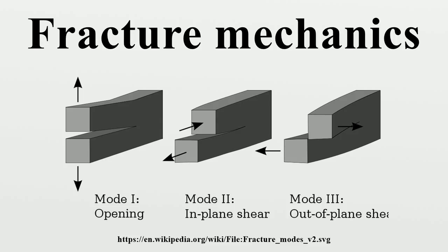Other approaches can be used to determine the possibility of further crack extension and the direction of crack growth and branching. A simple technique that is easily incorporated into numerical calculations is the cohesive zone model method, which is based on concepts proposed independently by Barenblatt and Dugdale in the early 1960s. The relationship between the Dugdale-Barenblatt models and Griffith's theory was first discussed by Willis in 1967.